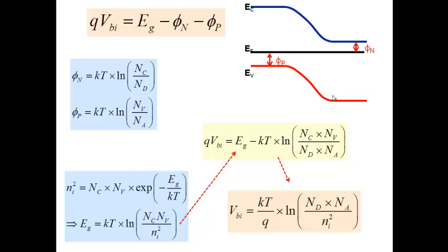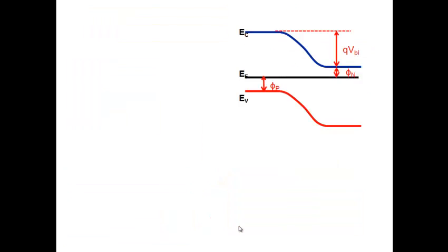So as I said, we have an expression for VBI, so it's fine. But I'll still calculate VBI now using two more methods, just to show you how we do analysis of semiconductor devices here. So n equal to NC exponent minus EC minus EF by KT. That's a very fundamental equation in equilibrium, right? So we start from here.